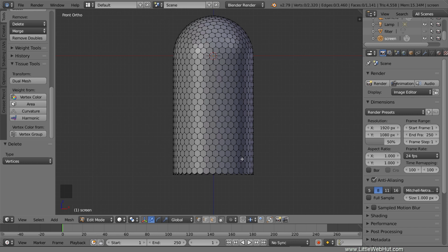The great majority of faces have 6 sides, but there are several faces that only have 5 sides and are a little smaller. We'll start by adding holes to the faces with 6 sides and then separately add holes to the faces with 5 sides. If we don't do these separately, then the holes in the 5-sided faces will look smaller than the others.